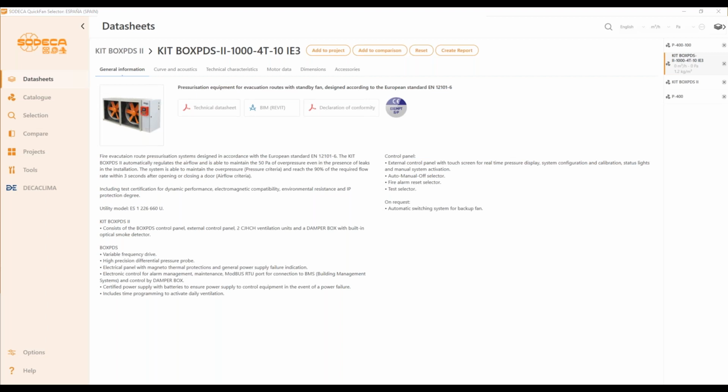But if we have to comply with the European standard, the 12101 Part 6, we have two options: either try to install the ductwork, or there is another option, but it's more complicated. It is to go to a performance-based design. Performance-based design means that we have to demonstrate that we have the performance that is required of the system with different kinds of calculations.